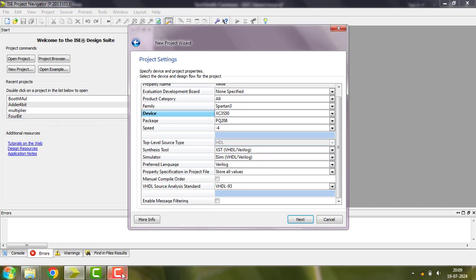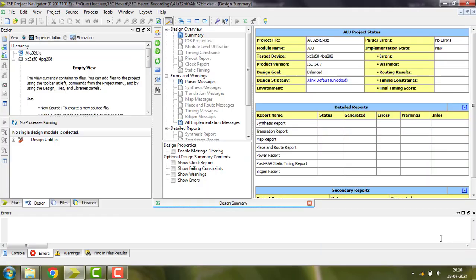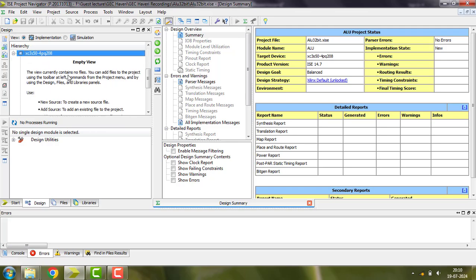I forgot that. Give me a minute. There is something called ChipScope for FPGA debugging. Even it supports the smallest devices like Spartan 3. In that ChipScope, you can give 32-bit inputs, or the simplest way to give inputs, you can even mention the inputs A and B in your code itself, the VHDL code itself.